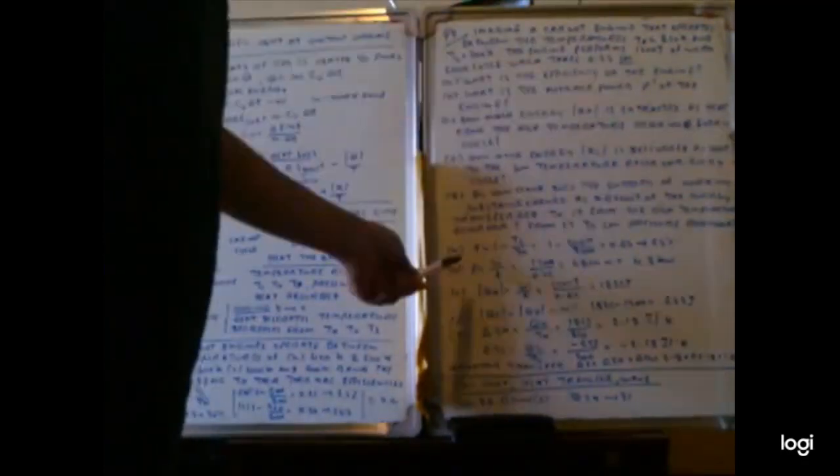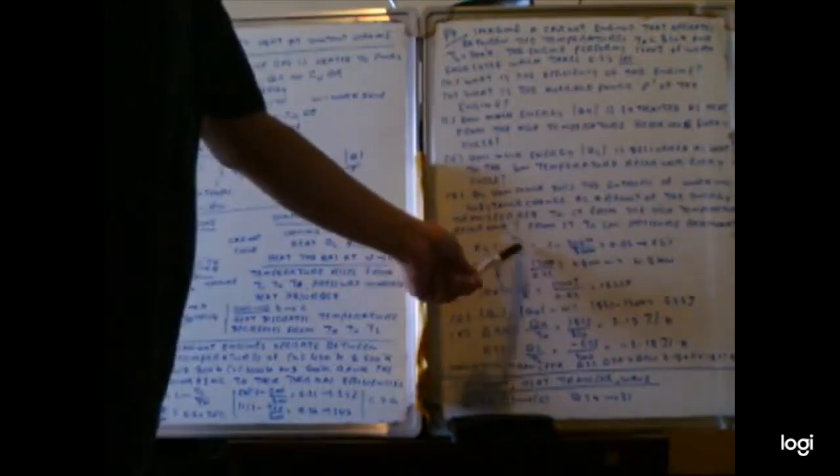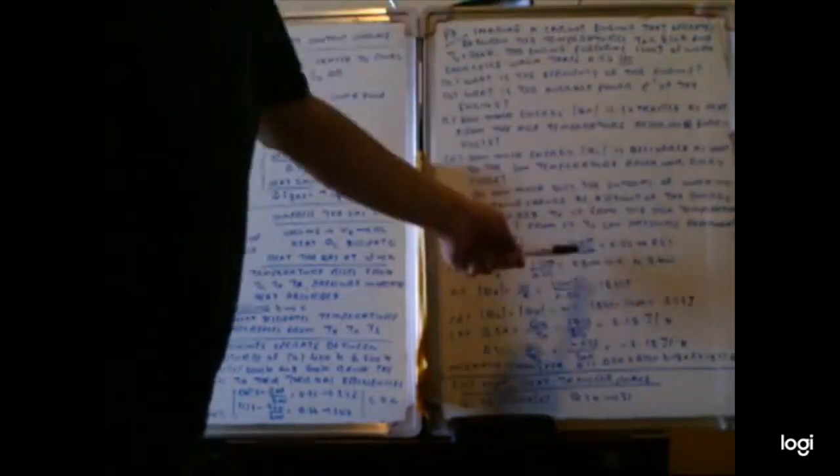First, this is a Carnot engine here, and the high temperature and the low temperature are given. Therefore, first you have to calculate the efficiency. Efficiency is 1 minus TL by TH. So the high temperature is 850 and the low temperature is given at 300 Kelvin.